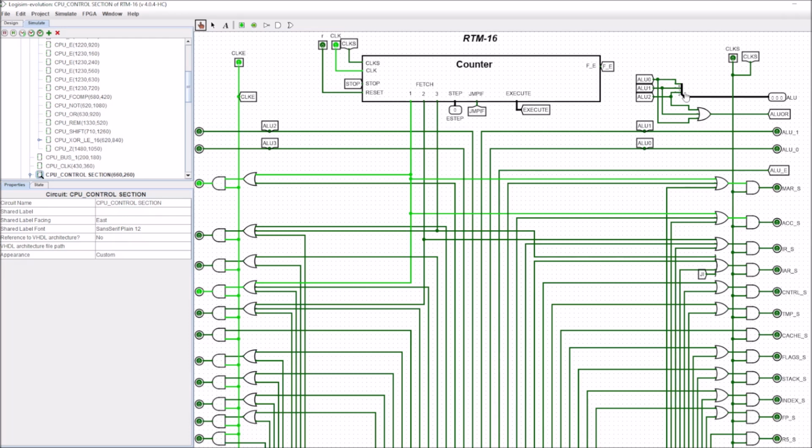So you can see here that I take a value out here, and that's going to be a number. If there's 3 lines, we'll have 2 to the 3, which is 8 different functions that we can choose within the floating point unit. So this output here becomes the select line for the floating point unit. Now another thing we do here is if any one of these values go high, it means that we have made a choice. So we've chosen a particular function within the ALU.